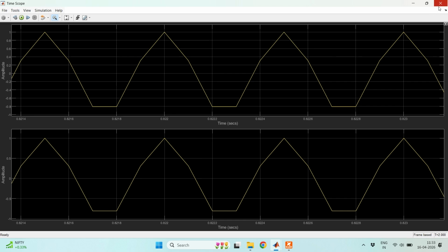So this is the fundamental reason, and you can also write it mathematically and verify it. We will not go through it, but you can actually do it and write it on paper and verify that 2 kilohertz sine wave will take identity of 8 kilohertz sine wave if you sample it with 10 kilohertz sampling frequency.